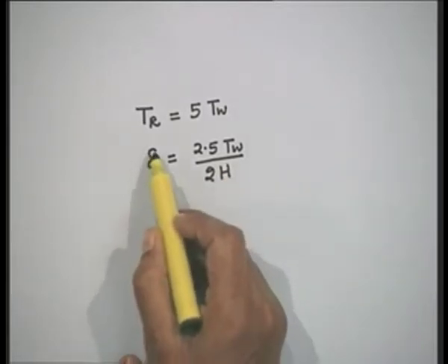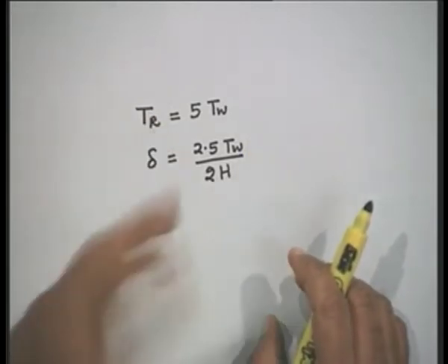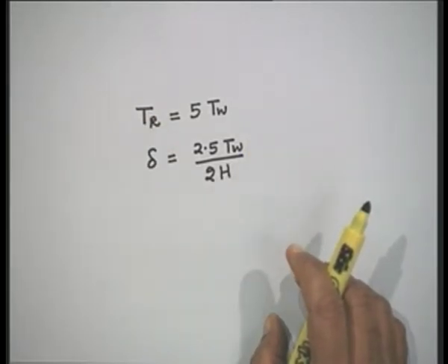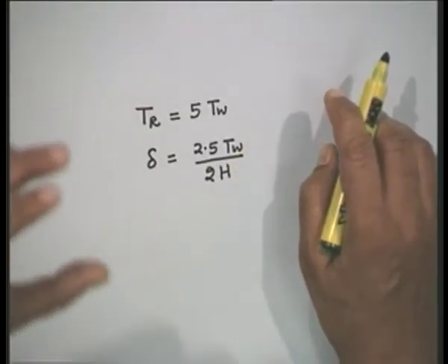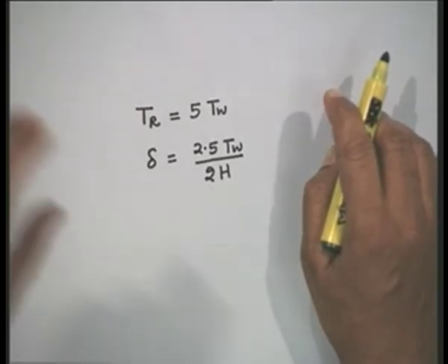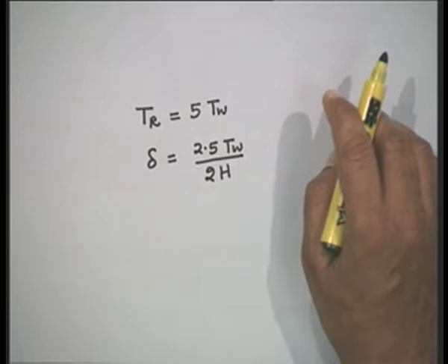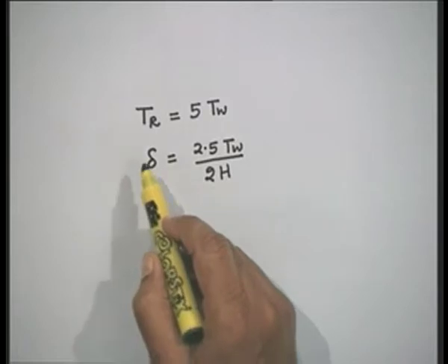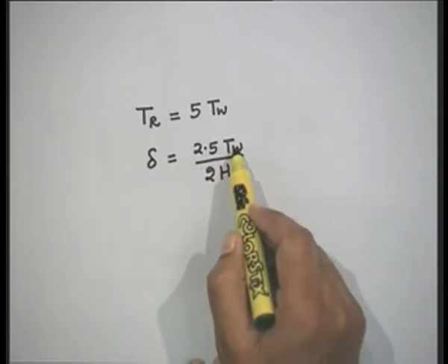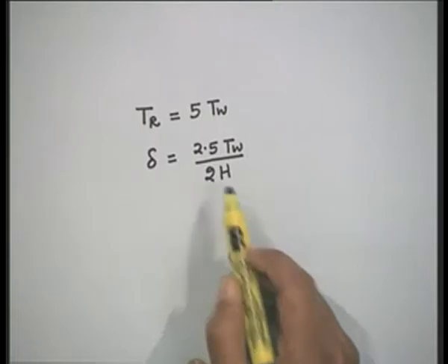Therefore, you can say that the temporary droop requirement depends upon the inertia constant of the turbine generator system and the water starting time, right, because as we discussed, this special feature that we have to provide, a temporary droop compensation, is particularly to take care of the special characteristic of the hydraulic turbine, and there is a relationship which relates temporary droop to water starting time constant TW and inertia constant H.